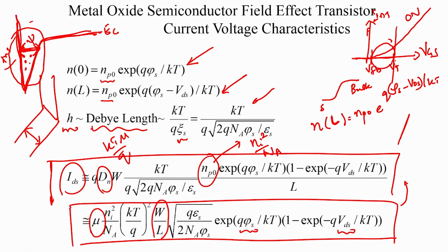Therefore, the current density in this region strongly determines the speed at which the MOSFET turns from off to on and on to off, and it is a very key parameter. The slopes or the time constants, or your dID by dVg if you like, are very important parameters to estimate how quickly the MOSFET turns on.